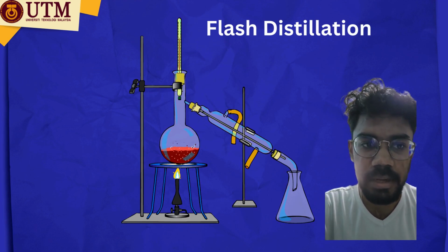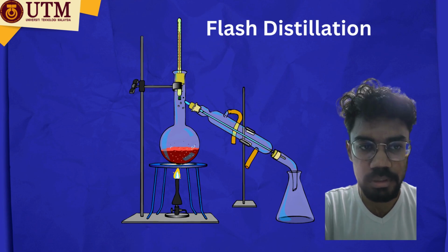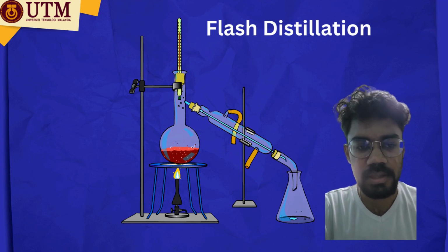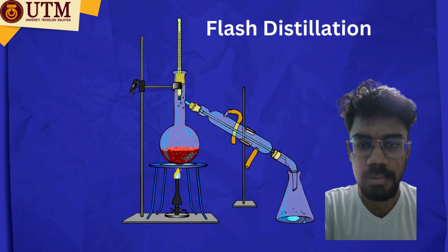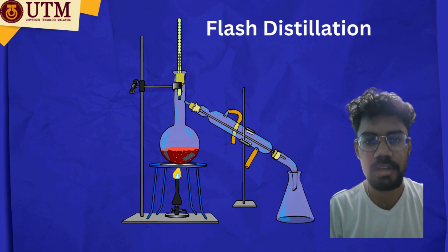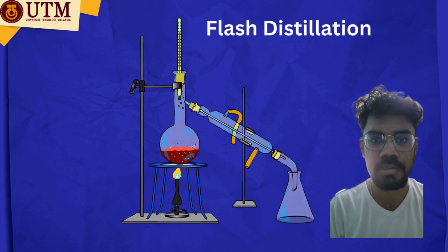What does that mean? The feed enters the flash distillation continuously and the separation occurs in a single stage, and flash distillation is not time dependent. Moreover, in flash distillation, the separation relies solely on the difference in volatility. No external medium such as steam is introduced.